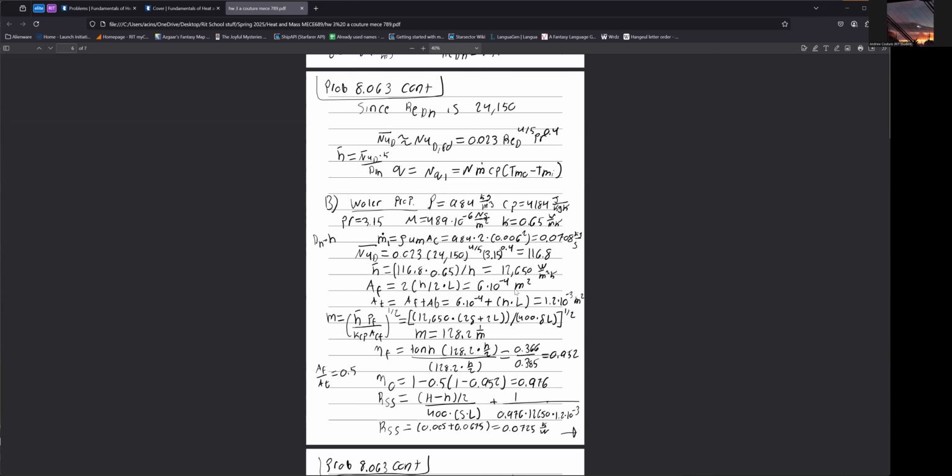To do that, we require the perimeter of the fins, the H bar, the H average, the K, CP, and cross-sectional area of the fluid, essentially. So you can see those numbers right here. We're pulling in H, the perimeter of the fins, the conductivity, and then multiplied by the area of the fins again, the cross sectional area, which gives us M as 128.2 1 over meters.